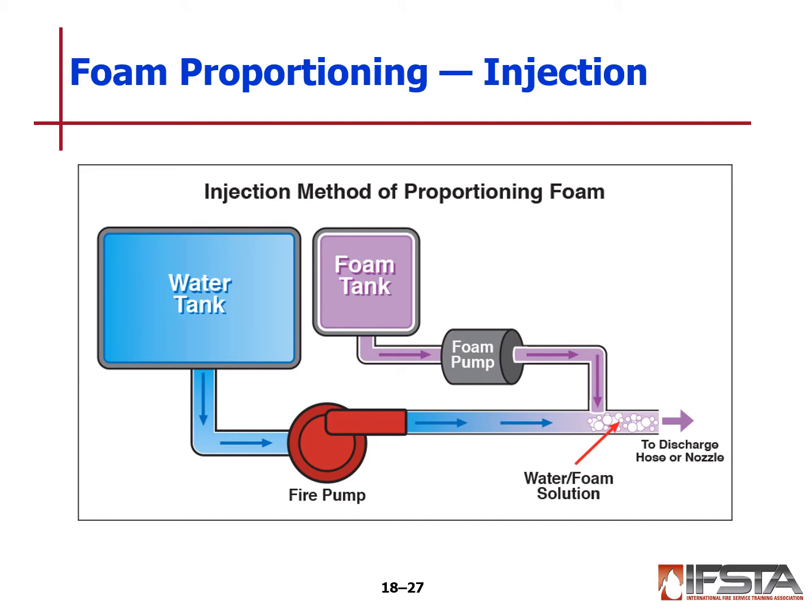An injection type system: water moves through the pump. The onboard tank of the apparatus has a solution pump that will inject a certain amount, depending on what we've set, to make the correct solution at the percentage of foam that we desire.